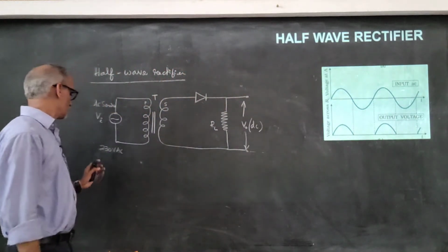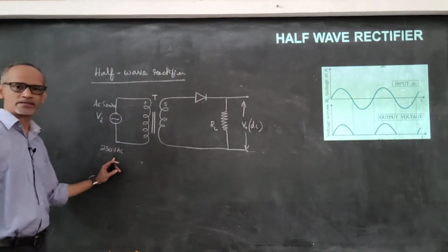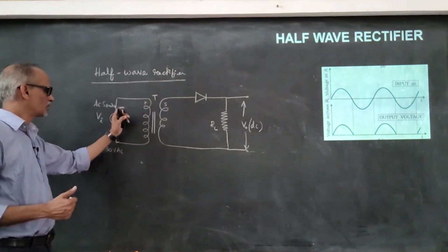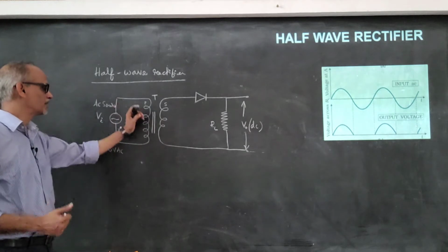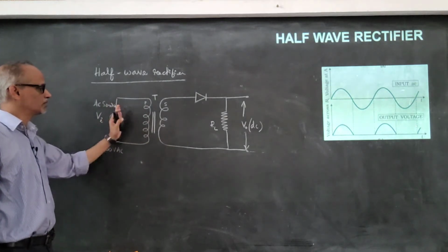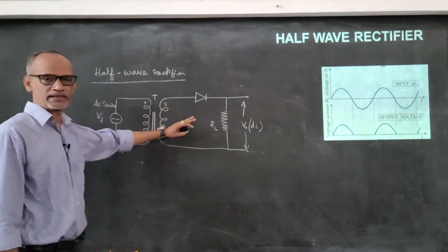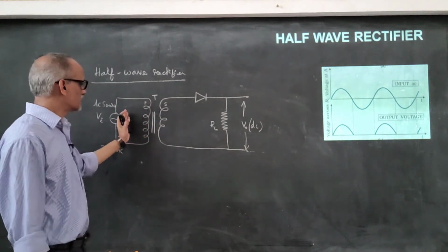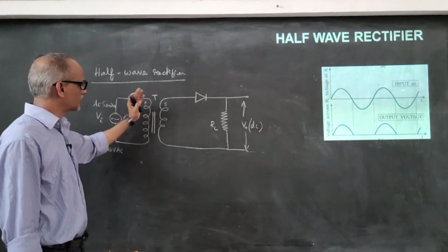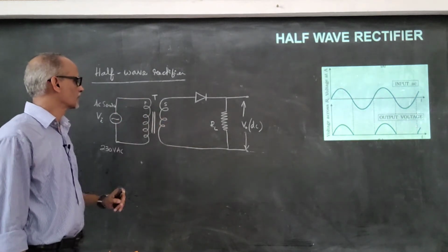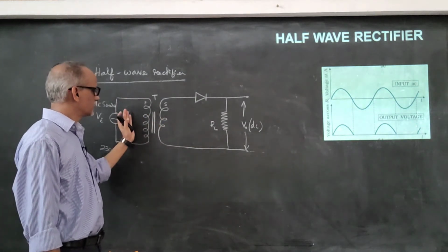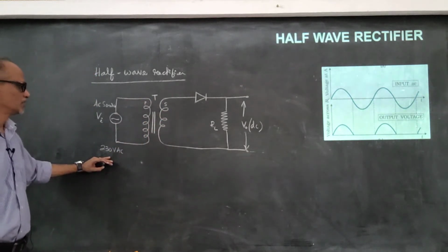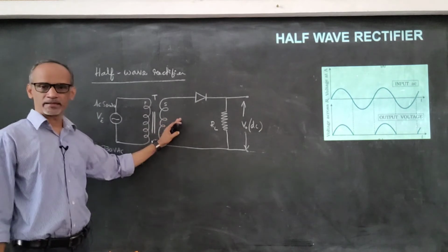Now this voltage is alternating, so that's why the voltage varies in the primary. Not only voltage, the corresponding current also varies in the primary, due to which it induces EMF in the secondary here. And since it is a step down transformer, the induced EMF will be lesser than that of the input. EMF induced in the secondary will always be less.